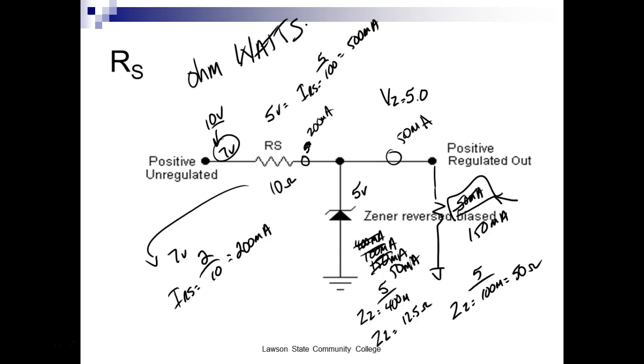And then a tolerance. Zeners have a tolerance. Right now, we're not talking about that, and we need to go back and look at that in a second. So Zeners, it might be a 5 point something volt Zener, but it's going to have a what? A tolerance. Resistors have a tolerance. Capacitors have a tolerance. So just about everything that we do is going to have a tolerance to it, right? You understand that?